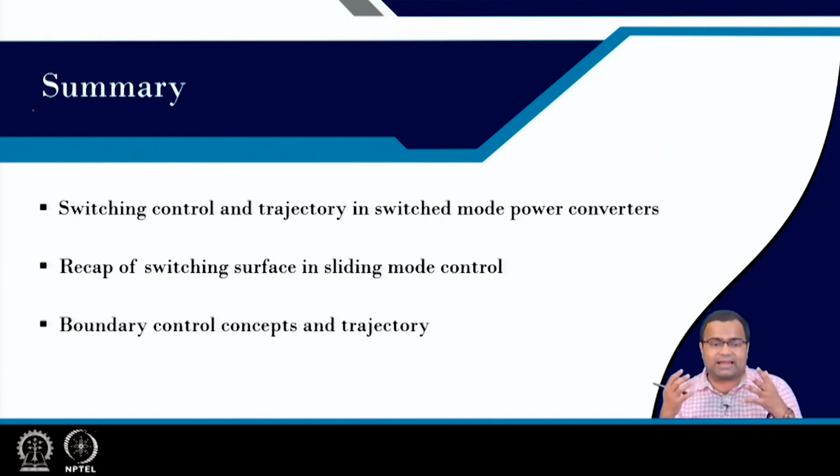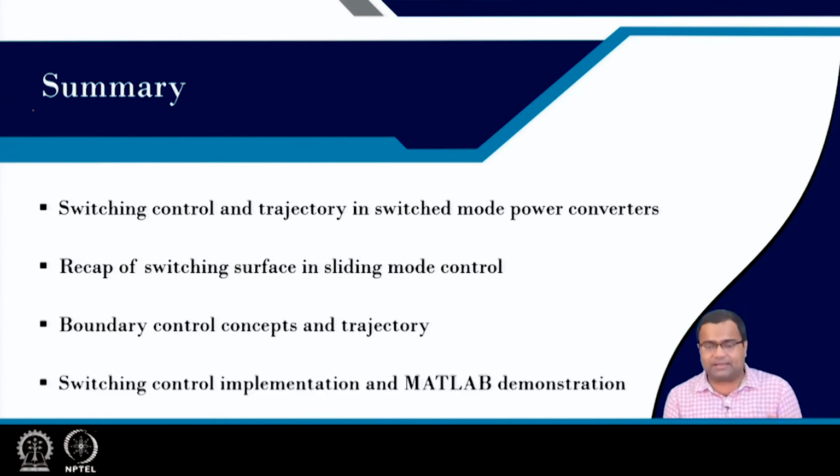But by doing that, we are going for a higher order switching surface, and that surface can be more intensive in terms of resource requirement and complexity. So, our target is to make the design simple and achieve something optimal, and use the PID controller structure we want to exploit. We have also discussed a few MATLAB case studies.